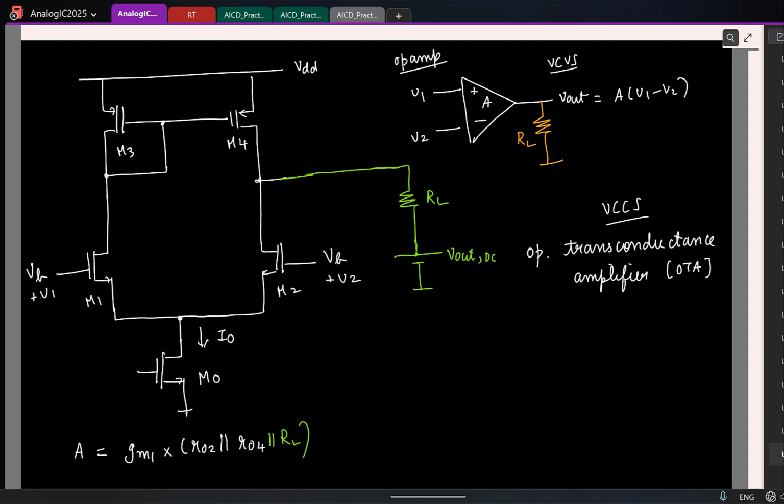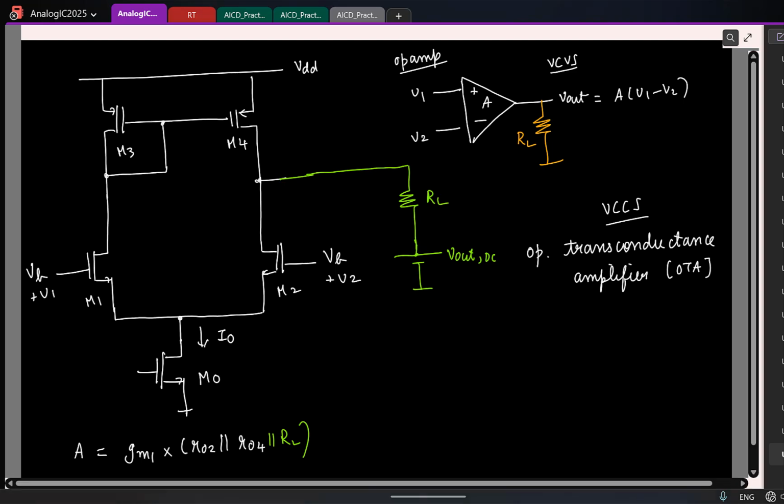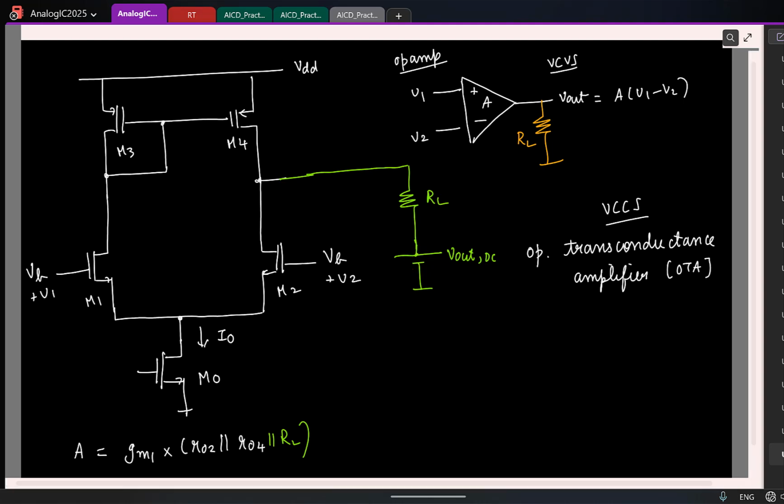Yeah. If we are using a source instead of a capacitor, then sometimes it would have a resistance comparable to RL. Yeah, if that is there, then I mean you can't do this. Assuming that you have a good voltage source, you can do this. So in practice, both are used, sometimes capacitor and sometimes source. Depends on the application. If the capacitor value is really large, don't do it. But if, let us say, you are looking at very high frequency operation, the capacitance value might be reasonably small, so then you can actually use it.